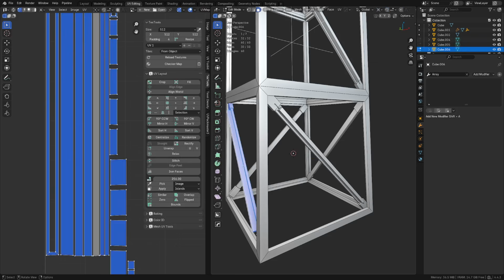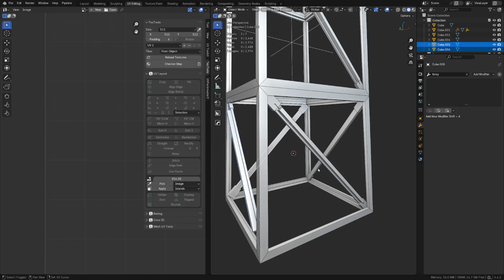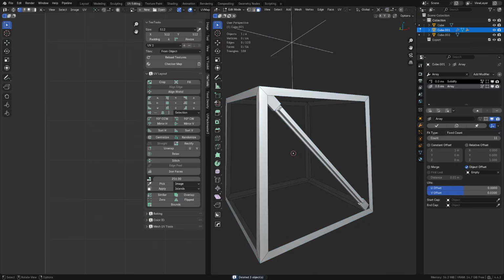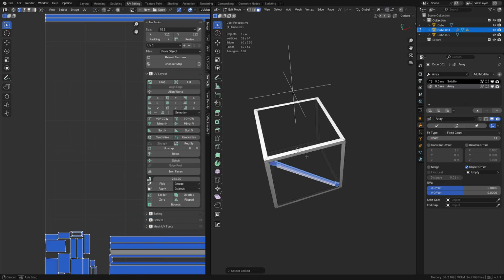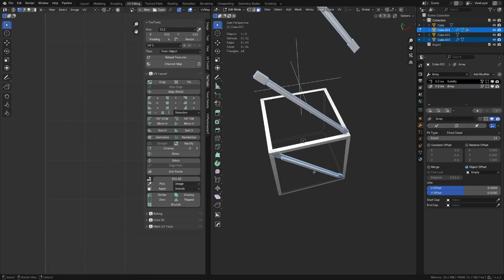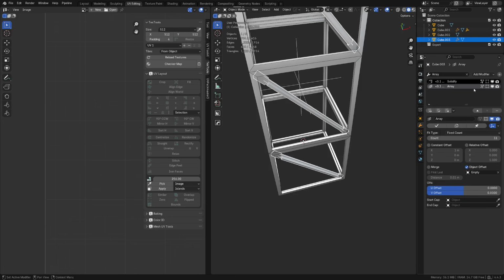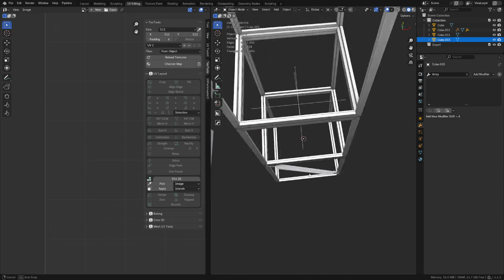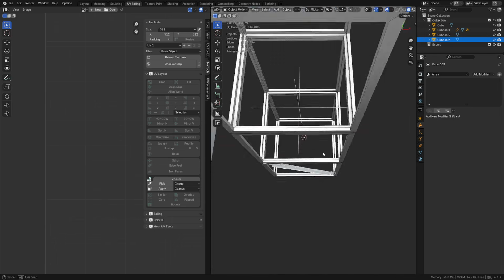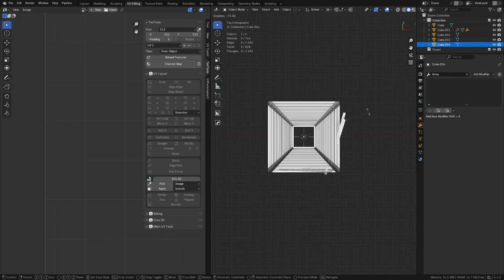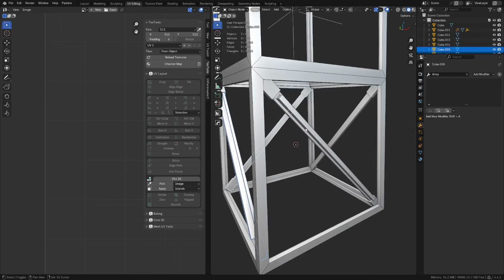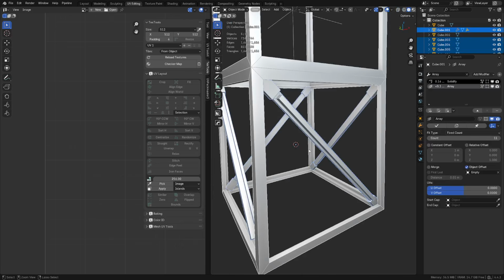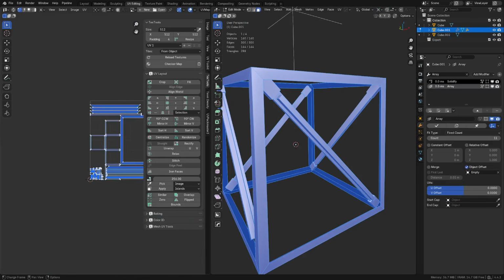So let's go through and grab these again real quick. Just get a hold of them. We can just grab this one, press L on it, because it's not joined to the other mesh. Okay, and we'll separate it even. Get rid of them. Usually you have the modifiers left over. You got to get rid of them. But then you can grab that one piece. You can Alt-D, R, hold Control, Shift-R. Okay, so they're all instanced. Grab them. Grab the base, Control-J, boom. And it'll all be like this.